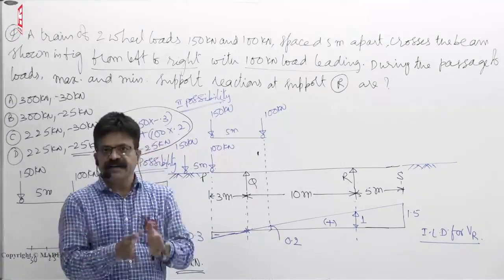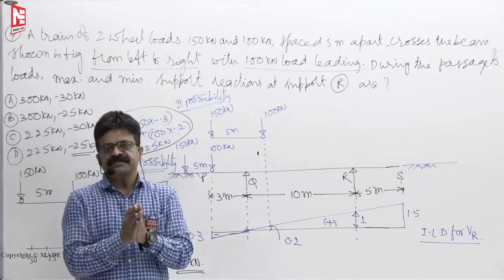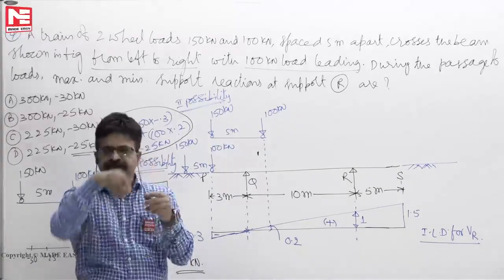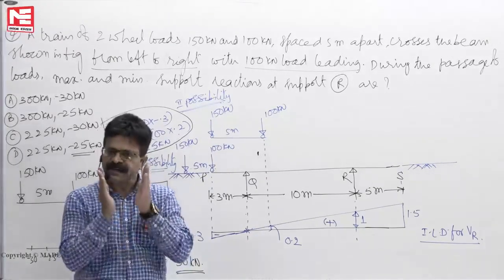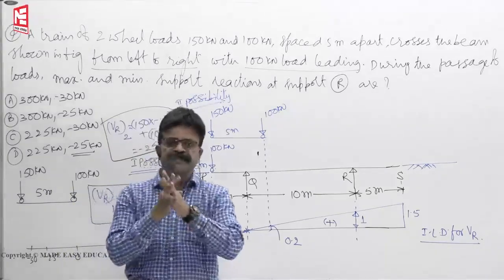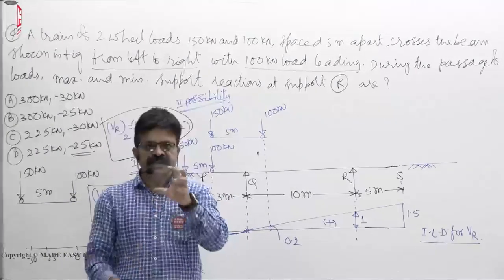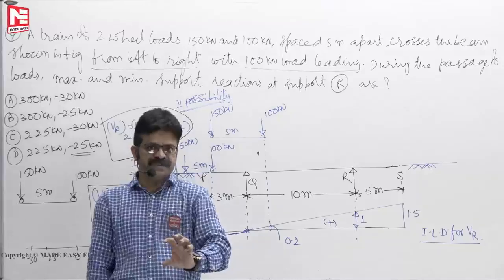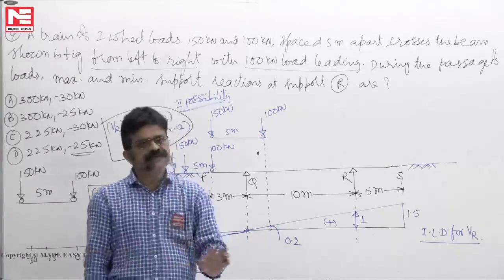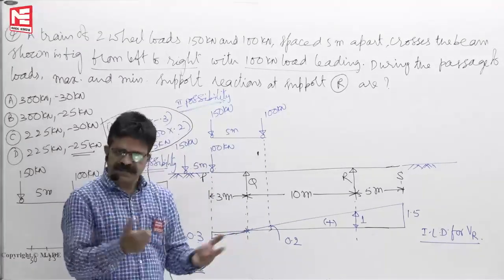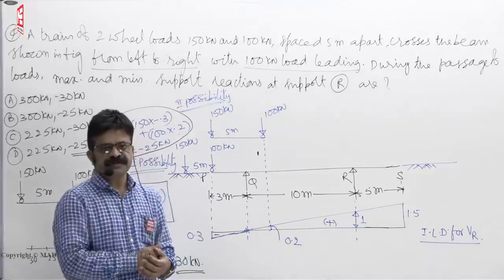Like that. Any element, whether steel or whatever, need not fail because of the major principal stress only. It can fail by the minor principal stress also. So that minus 30 is also a cause of failure, right?